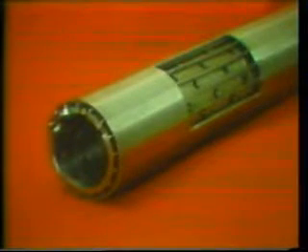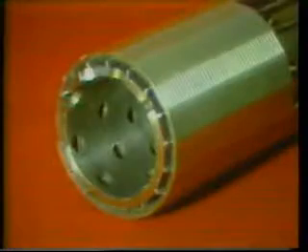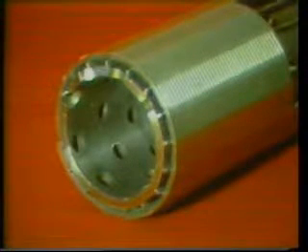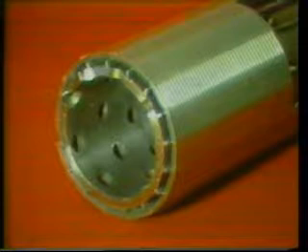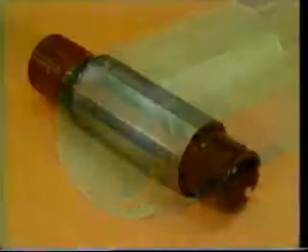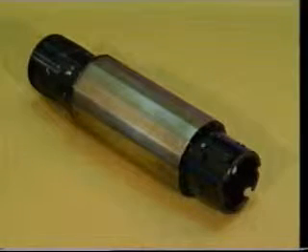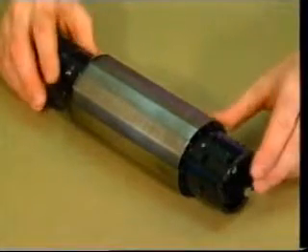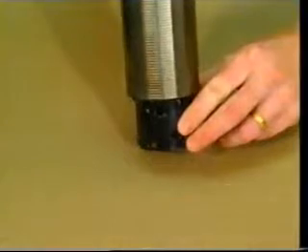Slotted liners may have the slots positioned vertically or horizontally. Vertical slots are more common due to strength considerations. Another kind of plane screen, the wire-wrapped screen, is a relatively low-cost sand control method. Though similar in cost and effectiveness to slotted liners, wire-wrapped screens have certain advantages that can make them preferable to slotted liners. These advantages are smaller screen size,